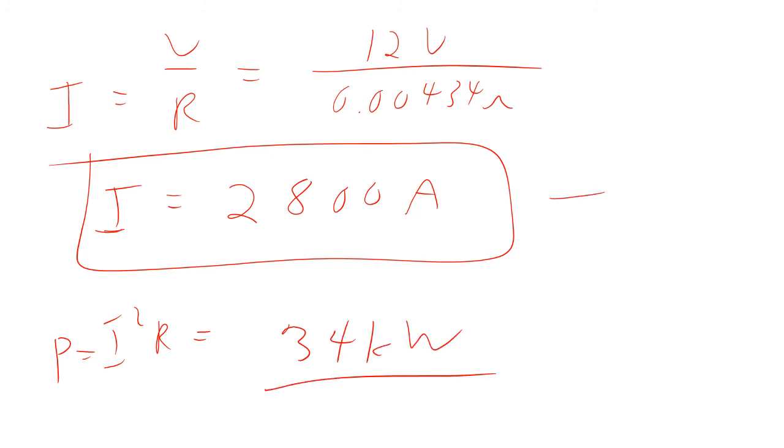Okay, so even though this is unrealistically high, it would still be a huge current that goes out, and so you'd still have a huge power dissipated. And what will happen is, if you leave it on there, it'll actually very quickly get so hot that A, it'll burn you if you try to take it off. B, the ends of it will actually melt the terminals of the battery and sort of weld it to the battery, and so it'll just keep going, but there's a limit to what the battery puts out because the battery has its own resistance. So the battery will start heating up, and when it heats up enough, you start boiling the sulfuric acid inside the battery, at which point the entire battery explodes. And that's going to be really annoying if you happen to be nearby.